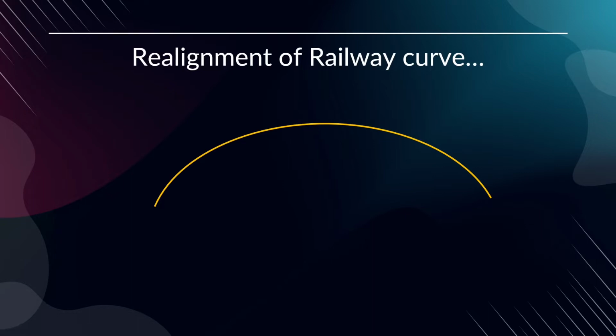So this is actually the circular curve. So long as it is a circular curve shape, this will be all right. As far as a curve is concerned, there will be a change of direction at every point. Because of the change of direction, centrifugal force will take place, and centripetal force has to counteract it. For that, we are providing super elevation.